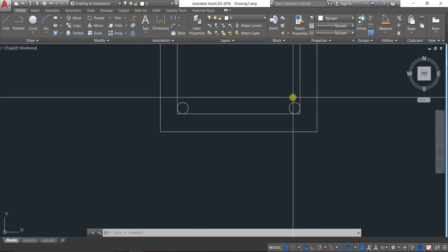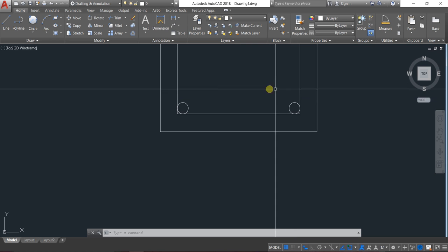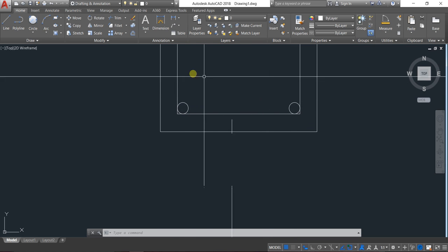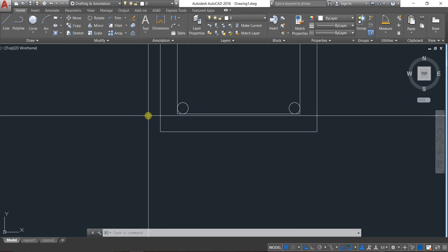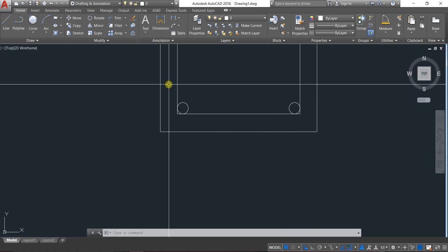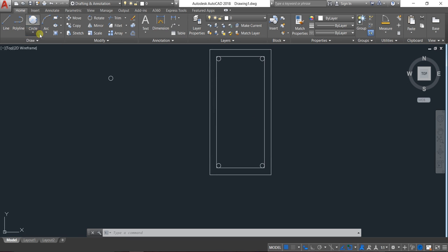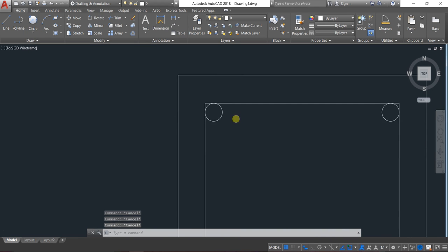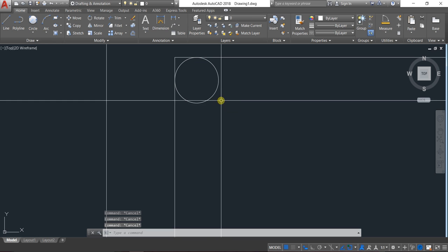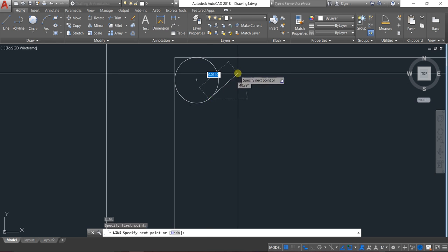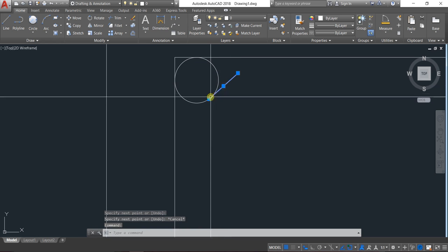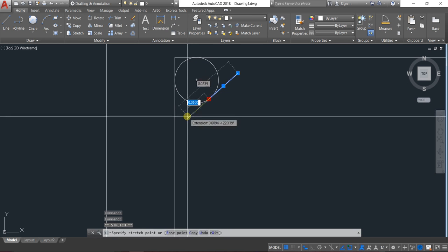Instead of creating one circle and copying and pasting it to one point then another point, it's much better to simply select this option, choose two lines, and hit enter by giving the radius. The third and last option over here is Tan, Tan, Tan. For instance, I have one line over here, maybe any line, and I extend it something like this.